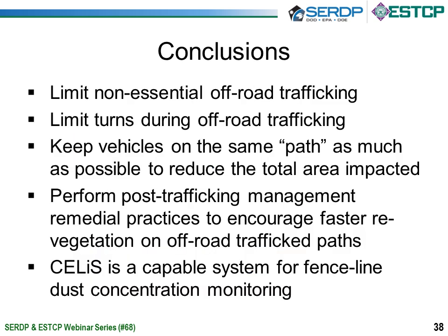And for the conclusions, any reduction of trafficking is beneficial to limiting military vehicle off-road dust emissions and after-traffic sites being susceptible to wind erosion. Therefore, limiting off-road trafficking to essential trafficking only should be the first management goal. If off-road trafficking is required, limit the amount of turning required, especially for the heavy and/or track-based military vehicles.